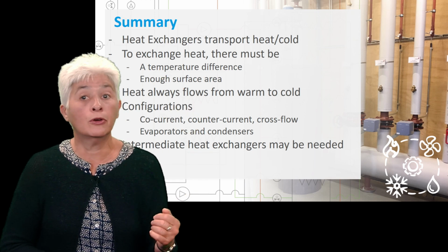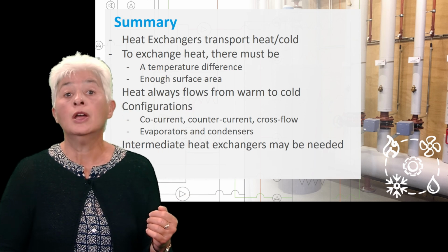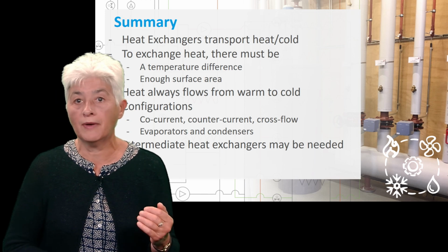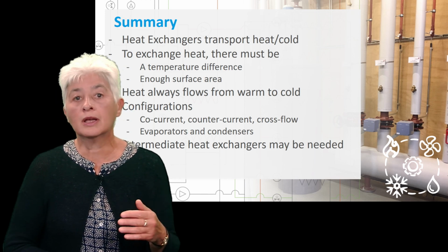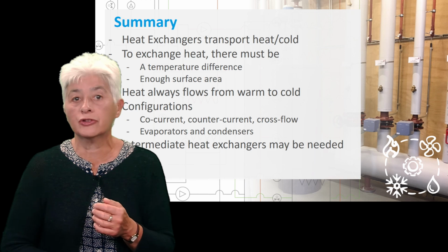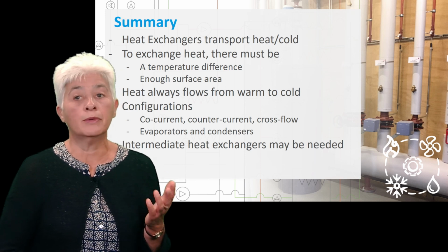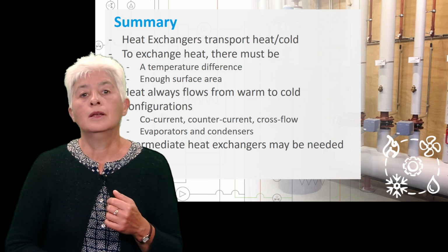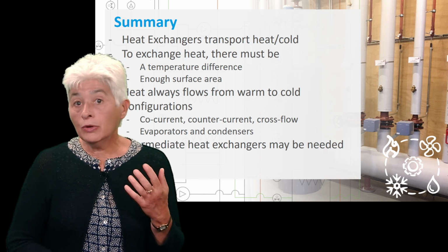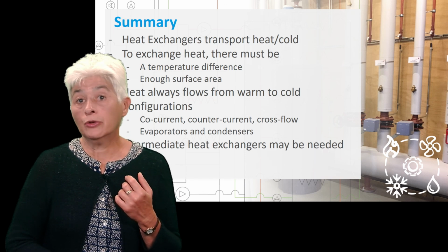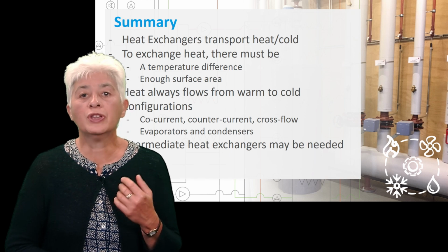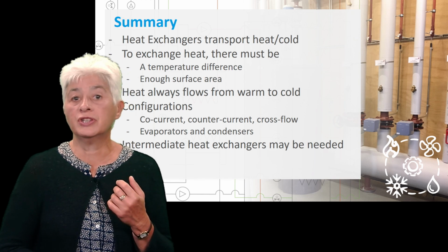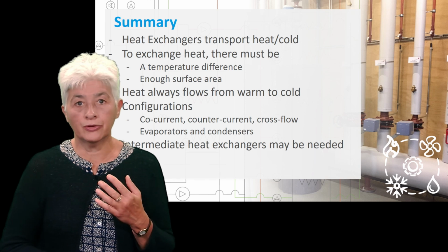We studied diverse heat exchanger configurations with their corresponding temperature profiles. This includes co-current, counter-current and cross-flow heat exchangers, as well as evaporators and condensers. And we also studied the temperature consequences of having to use intermediate heat exchangers for safety or legal reasons.